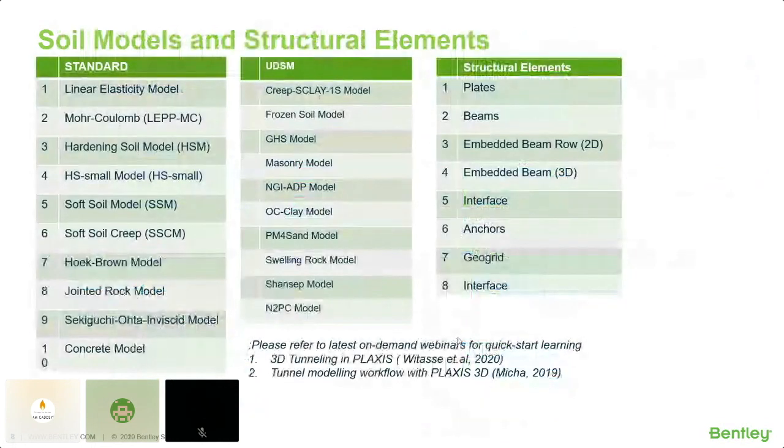Now, in addition to modeling the geometry correctly, one should also take care while choosing the correct material model for the analysis of any geotechnical problem. Plaxis has an extensive soil model library for modeling of clay, sand, and rock. In Plaxis we also have two sets of models, the standard soil models and a user-defined soil model, that can be used for modeling any particular type of problem.